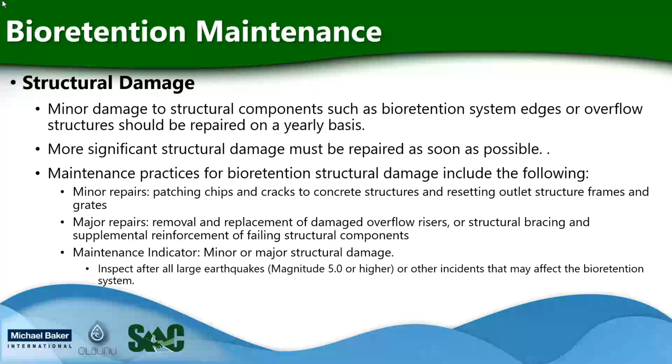The lifespan of bioretention systems can be up to 20 years and potentially longer if properly maintained. Bioretention lifespans depend significantly on the maintenance of the bioretention system and stabilization of the bioretention system drainage area. More sediment entering the basin equates to a reduction in bioretention system lifespan.